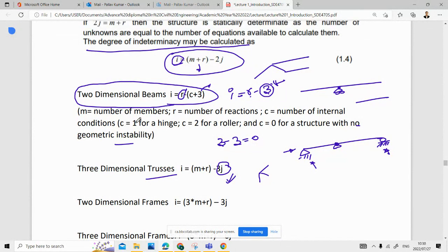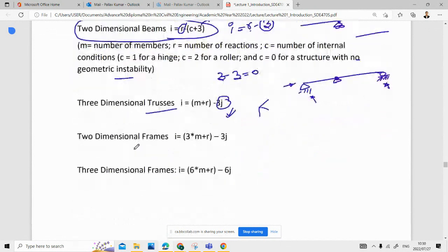Yes, sir, I understand that. But now, for example, on a truss, at each support, depending on how it looks, it could be a joint of members as well. Yes, definitely, but that support will be treated as a reaction. That is not a joint. A joint is just a hinge joint. You can't treat it as a support. If anywhere in the truss you have any other support, you will treat it as unknown reactions. Remember that.